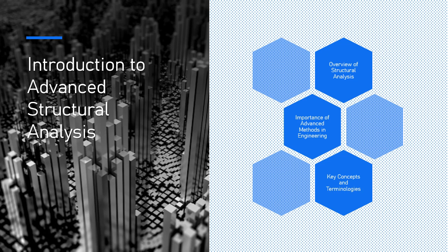Fixed: the structure is constrained in all directions at the support, with no displacement or rotation. Pinned: the structure is restrained from translation but can rotate. Roller: the structure can translate in one direction but is constrained in the perpendicular direction.